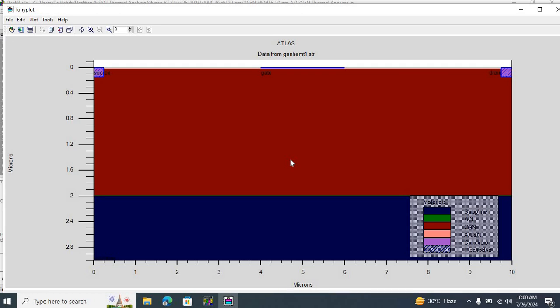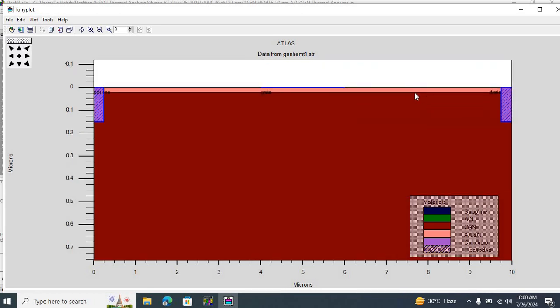That is a heterojunction. For example, over here, if I zoom in on this structure, we have an aluminum gallium nitride material, this thin layer over here, on top of a gallium nitride material. So we basically over here at the interface have a heterojunction. And a high electron mobility transistor utilizes this heterojunction to demonstrate the field effect transistor.